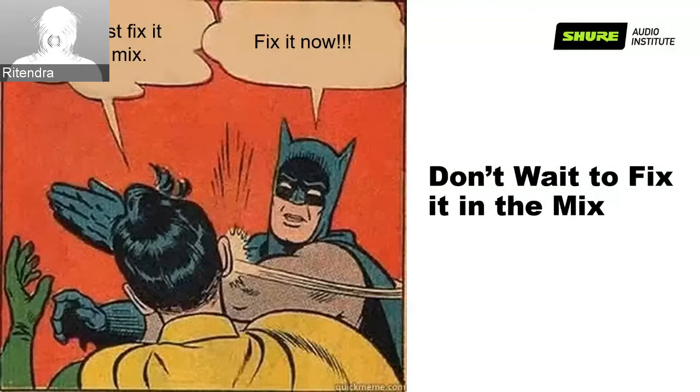While it may be tempting to buy a different microphone or more expensive DSP processors, the best investment you can make is in improving the acoustics of the room upfront. Making a positive change at the beginning of the signal chain impacts the entire system performance. So no need to wait to fix it in the mix. You can work on treating the room properly, and that can help a lot. And then you hardly need to look at the DSP processing.